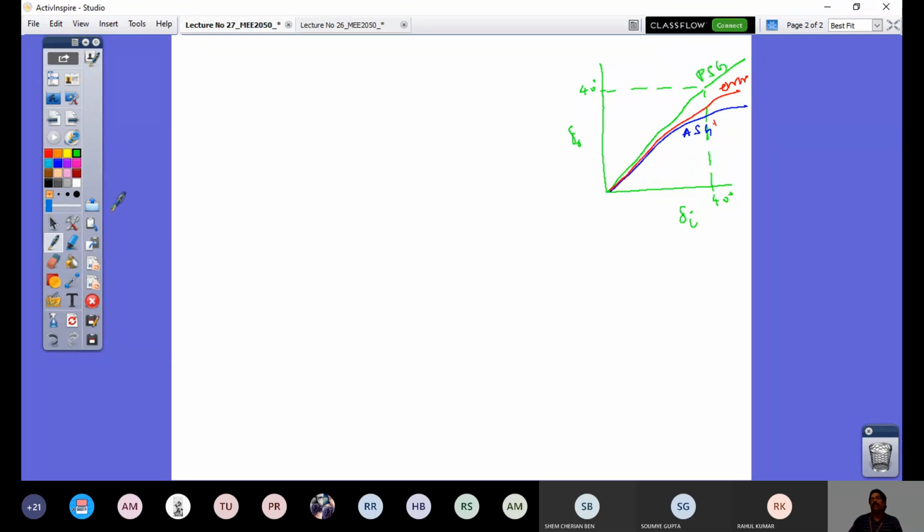To get this variation, I am going to consider a front fixed suspension. It's not an independent suspension, it's a fixed beam suspension, and I have my steering geometry there, the planar steering geometry, for simplicity. So let me draw the top view of my contact point rectangle. This is my track and this is my wheelbase.